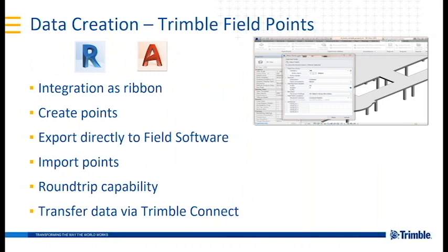So we have a couple of ways. The other way of creating this data and preparing it ready to go out onto site is a plugin called Field Points. This plugin is available for both Revit and AutoCAD. Again, it's a very simple piece of software, but very effective. When we tell people they need to create data to set out, they can get a little concerned, because you have to create a point. A point is the XYZ coordinate of what you're setting out. It's a very automated process using this software: you can embed points and markers within families and within groups. It's a very simple way of exporting it, and then you just export that model out onto the tablet as well. And this also works for Tekla.